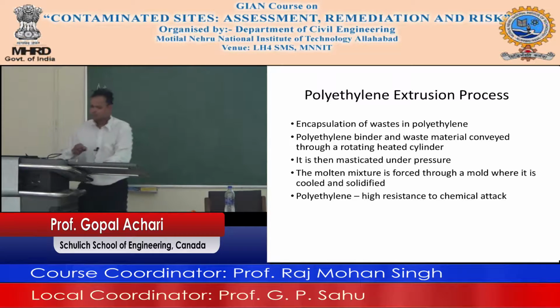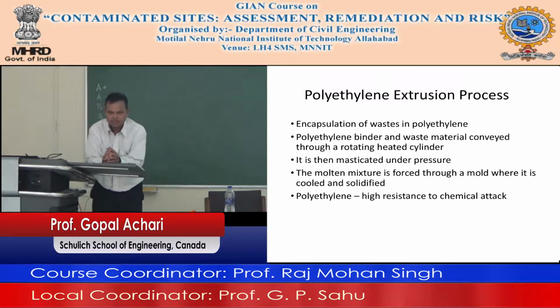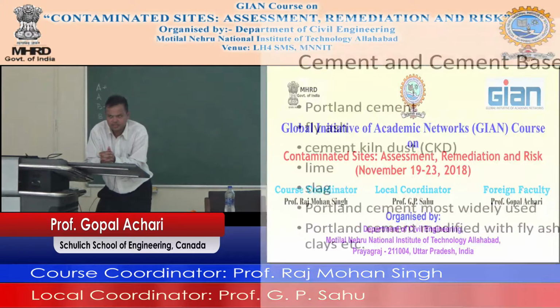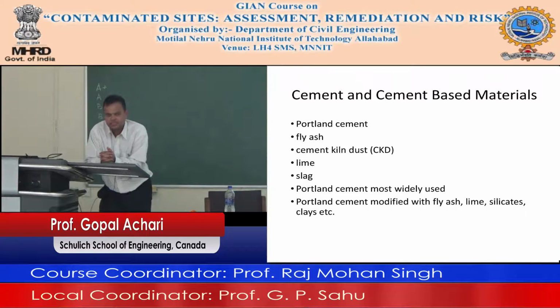Now to come to the most widely used solidification stabilization technique, which is cement and cement based materials. By far the most widely used method. In cement and cement based materials, we have Portland cement, fly ash, cement kiln dust, lime and slag.